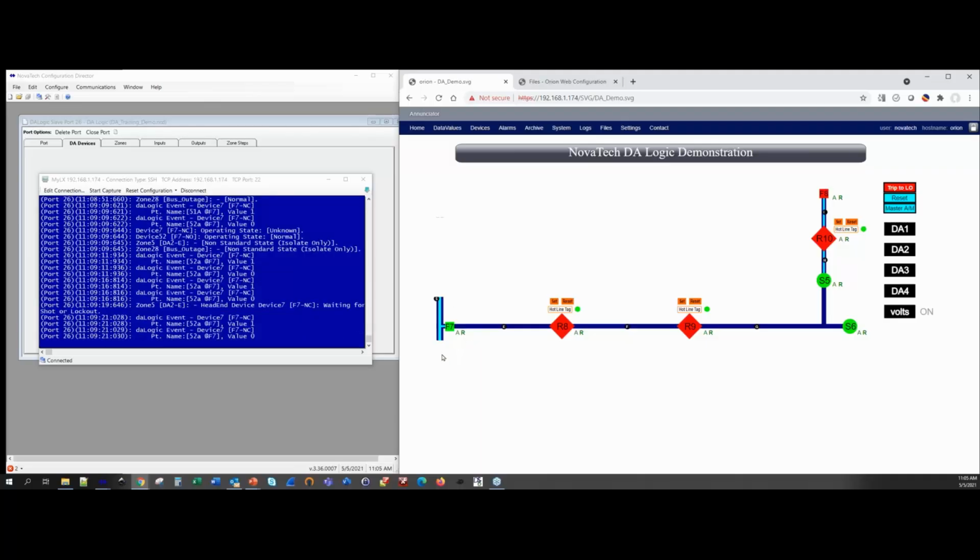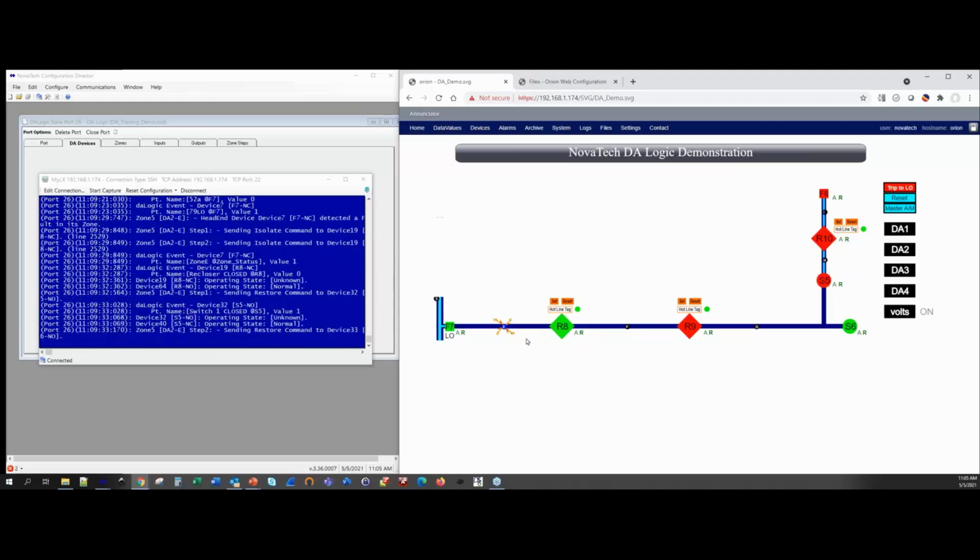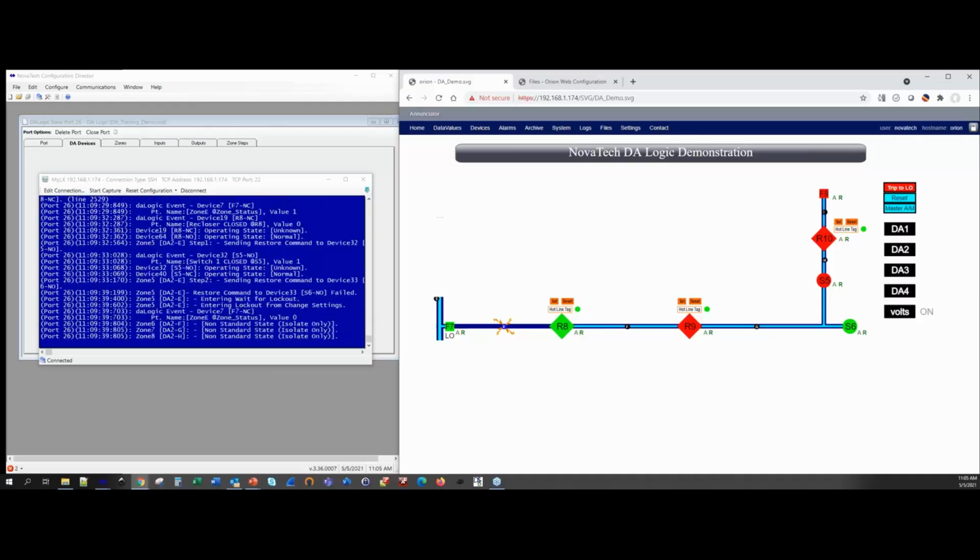Okay, here we're going to see this go to lockout. Now that we have lockout, it's going to locate that the fault was in that location, open up recloser 8, switch to switch 5, and restore power from feeder F8.